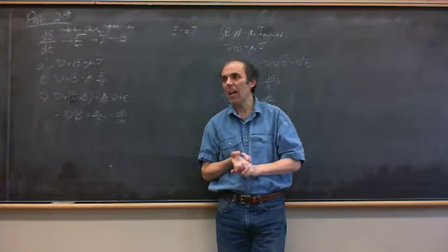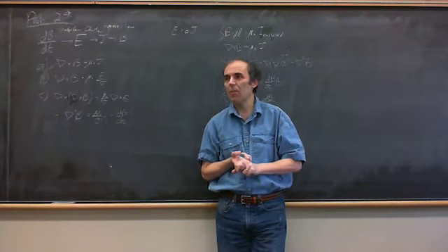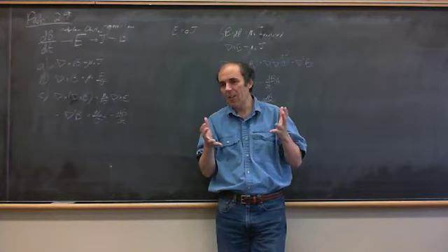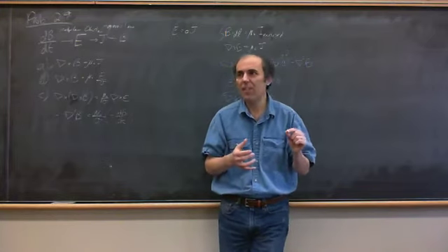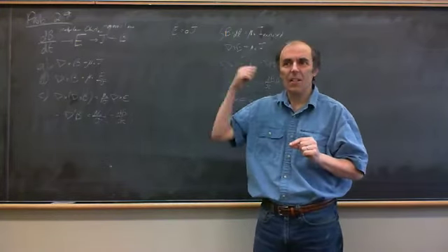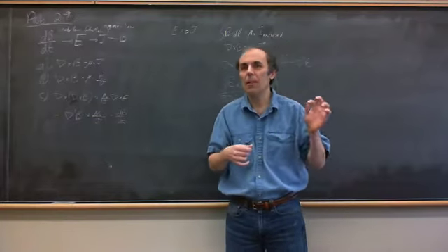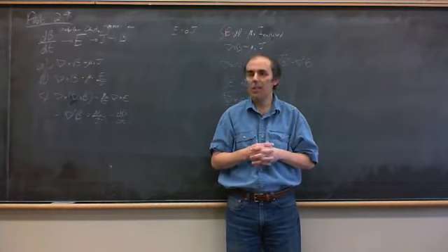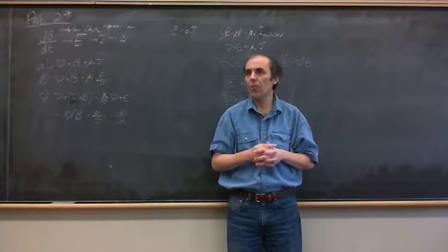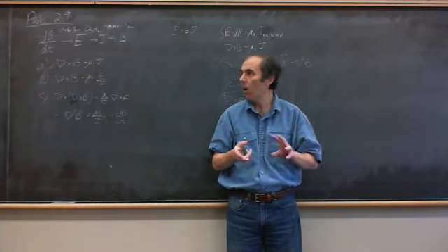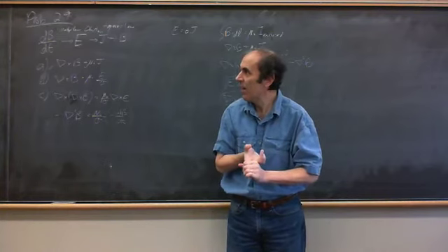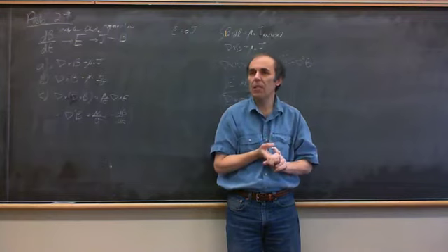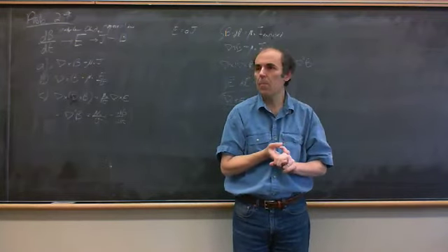But there are cases where skin depth can be important, but it's not magnetic stimulation, and it's not really MRI. You have to go up to really high frequencies. Of course, skin depth in a wire is a lot shorter because the conductivity is 1,000,000 times higher than it is in our bodies. So skin depth in wires happens when you just get up into radio frequencies, but for a body it takes huge frequencies. Okay, so that is a little bit about Faraday induction and its applications in health and in humans.